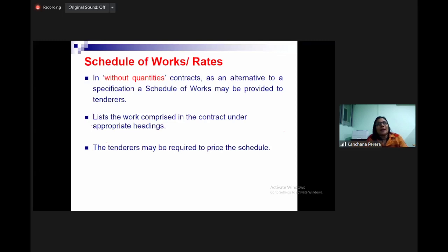Transferred to the drawing and spec. The bidder must see it as well. But rates are taken. So we do not stick to the what? If it is a lump sum project, if there is a schedule of rates, it's high risk to the contractor. If it is a remeasurement contract on a schedule of rates, it's less risk to the contractor. Why? Quantities will be measured and paid. Right? Can you understand that? Any question you would like to raise?